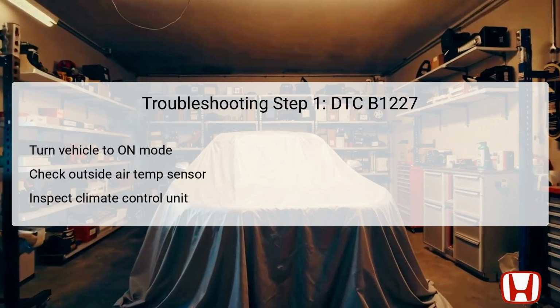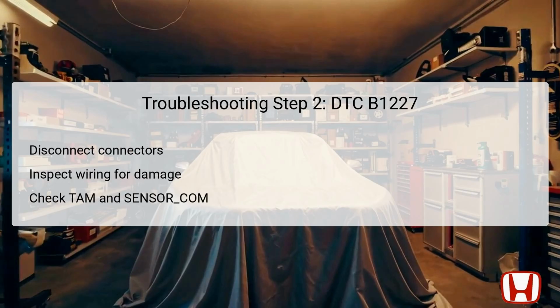By starting this step, you establish a baseline to pinpoint the fault, whether it lies with the sensor or the climate control unit. The second troubleshooting step involves disconnecting the connectors for both the outside air temperature sensor and the climate control unit. Once disconnected, inspect the wiring thoroughly for any signs of damage, such as fraying or corrosion, which could create an open circuit and trigger the DTC. Specifically, check the TAM signal circuit and the sensor COM ground circuit to ensure they are intact and not shorting or open. By carefully examining these components, one can isolate potential faults before proceeding with further diagnostics.